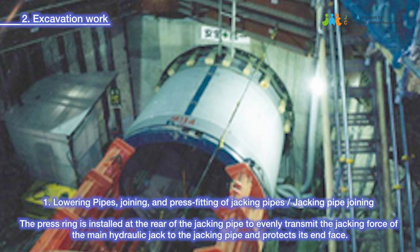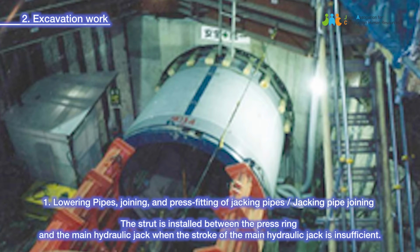The press ring is installed at the rear of the jacking pipe to evenly transmit the jacking force of the main hydraulic jack to the jacking pipe and protects its end face. The strut is installed between the press ring and the main hydraulic jack when the stroke of the main hydraulic jack is insufficient.